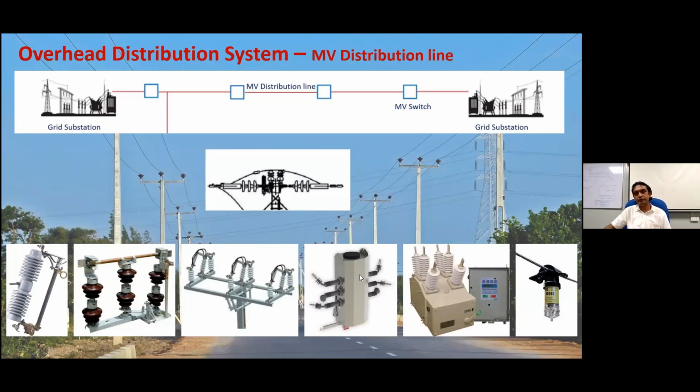It's called a load break switch. In a simple way, the LBS has the same operation as the air break switch, but the medium of arc quenching is different. It is SF6 gas. It's also a mechanically operated switch. We can also control it electrically by a motor-driven unit. Again, we can operate it remotely by integrating a remote terminal unit.